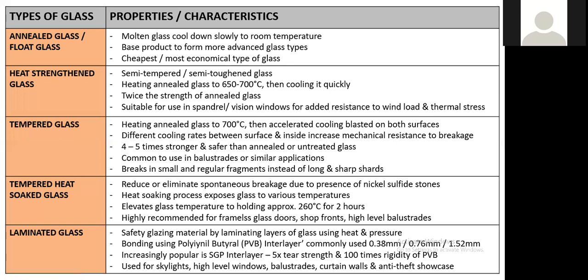So maybe you have your outdoor baluster, which is exposed to heat, and then you want it to have more strength. Then maybe you should spec tempered heat soaked glass, okay, instead of just tempered glass. All right. So the last one is